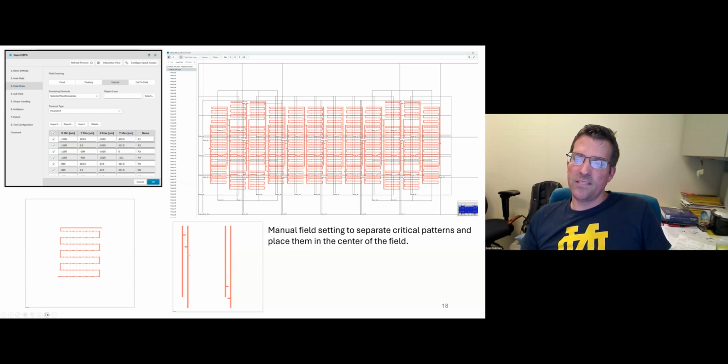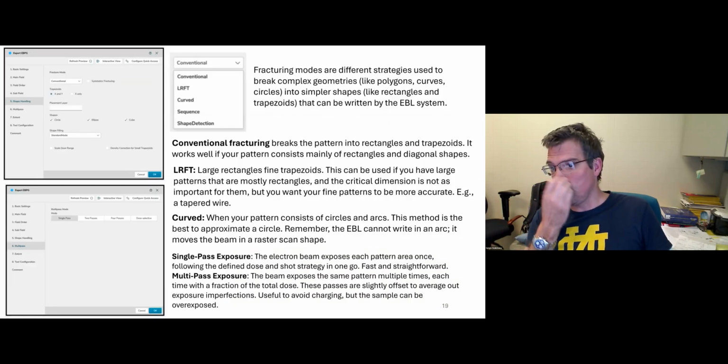And then these big lines, which are like 10 micron wide, long interconnect lines, are not a critical feature in terms of stitching error. So they can move a little bit to the left or right, and it's not going to cause any issue. They will still be exposed, and a very small shift doesn't cause any issues. So this is just one of the tricks that I suggest using.